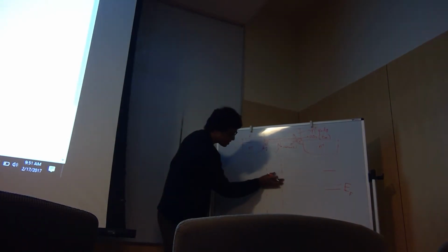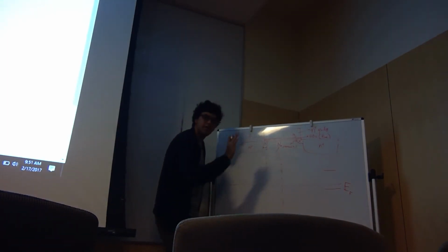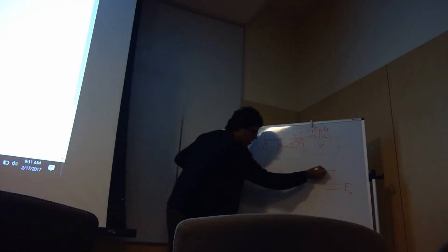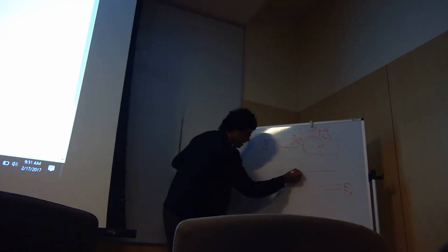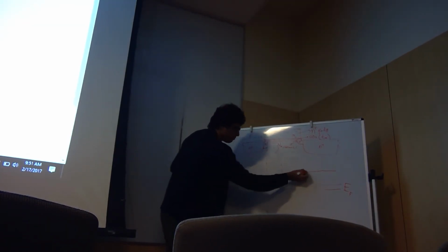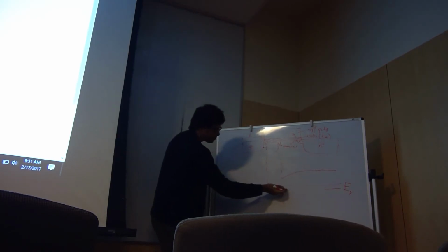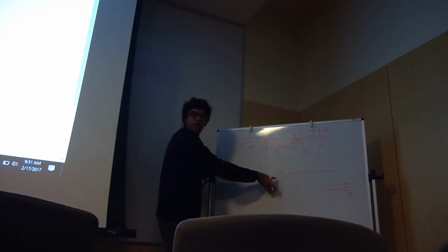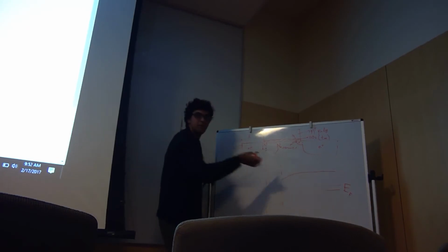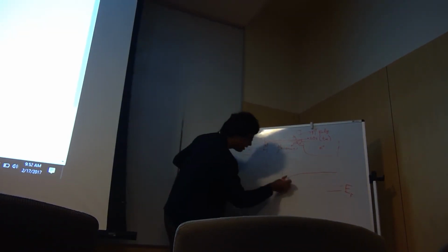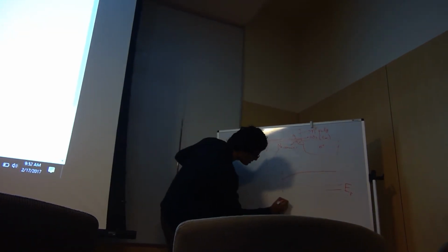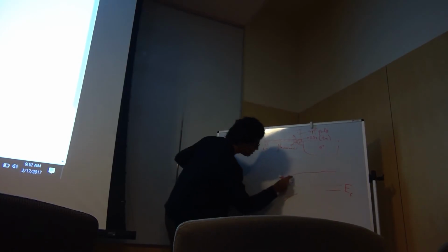Now, because my electrons had gone here, this region will have more electrons, so the conduction band will bend closer to the Fermi level. That simply means there are more electrons here, because this gap determines the electron concentration. And because your band gap has to be fixed, your valence band will follow this conduction band and look something like this.